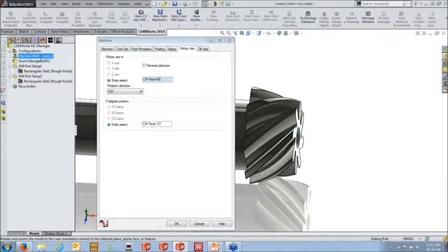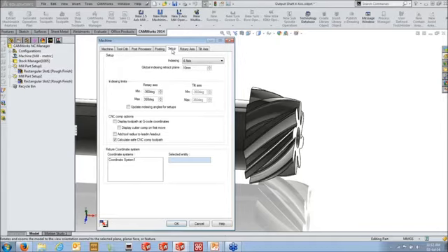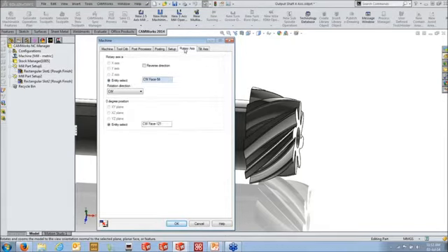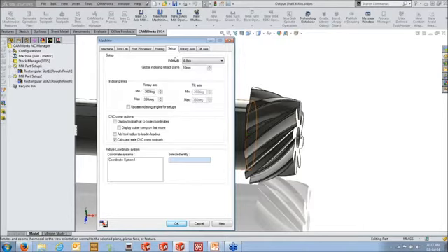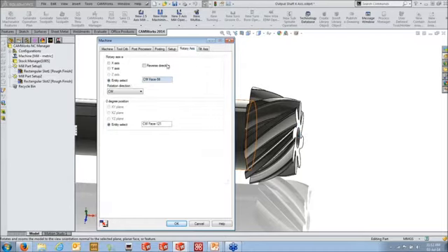So I go back into the machine, go back to my setup tab, and rather than using the rotary axis from a particular face, it needs an actual axis and a coordinate system defined. So that coordinate system is selected right here. And as soon as we select that coordinate system, rather than using the face to define it, we can use the axes to define it here. And by defining the x-axis, it knows to switch the y-axis to the rotary move.